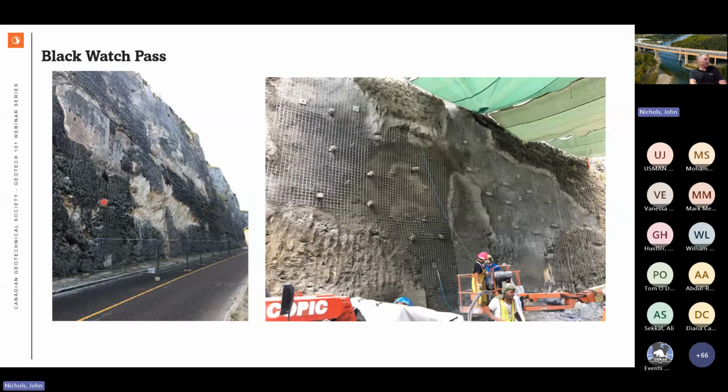Next, we had this big erosional feature that was clearly undermining the entire slope. Over time, it was getting worse, and this is what the client was telling us. So the real solution there was to ensure that we protected that weaker area with some shotcrete, protected it from further erosion, but also gave it some support for up above.